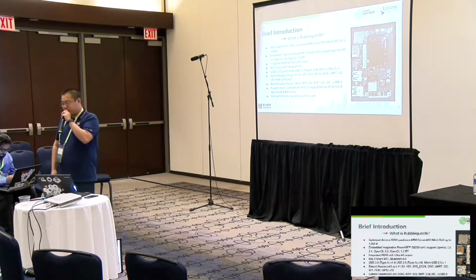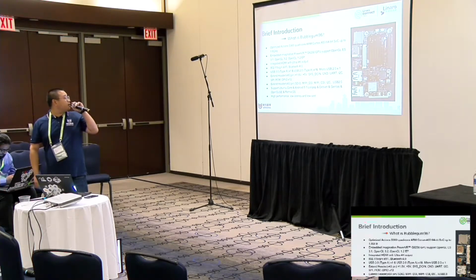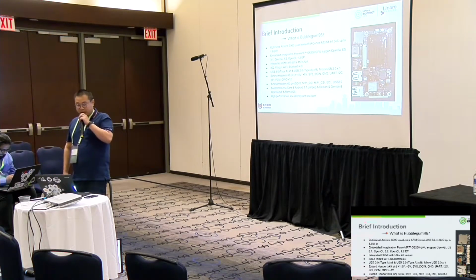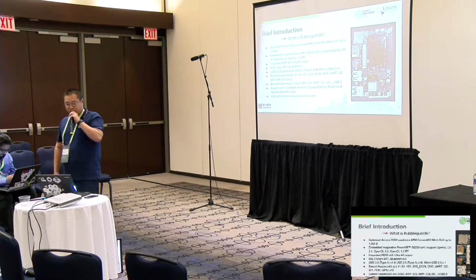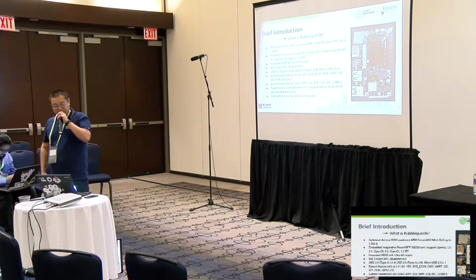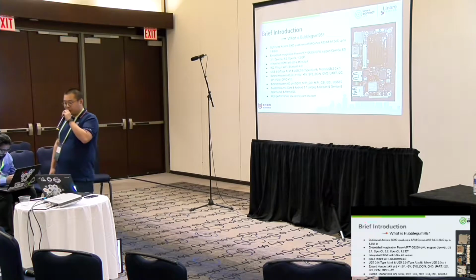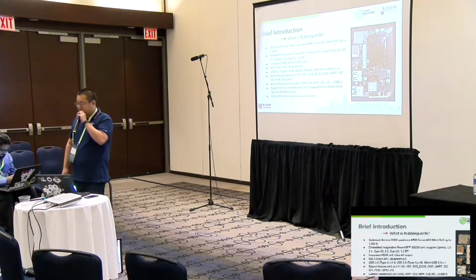On the commercial edition 96 board, we have 40 pins of low-speed extenders, which provide the power supply, system DC in, ground, UART, I2C, SPI, PCM, GPIO, and 60 pins of high-speed extenders, which provide SDIO, MIPI-CSI, MIPI-DSI, I2C, USB.